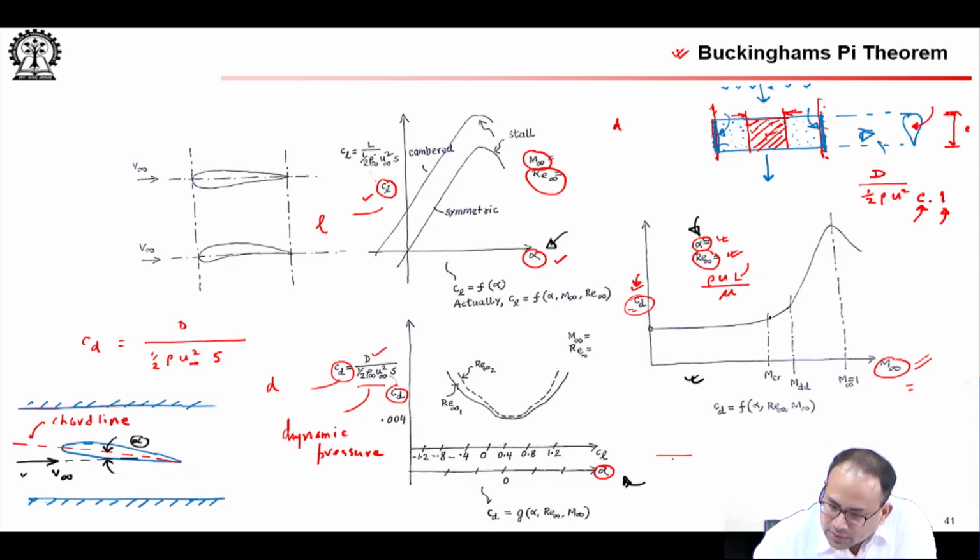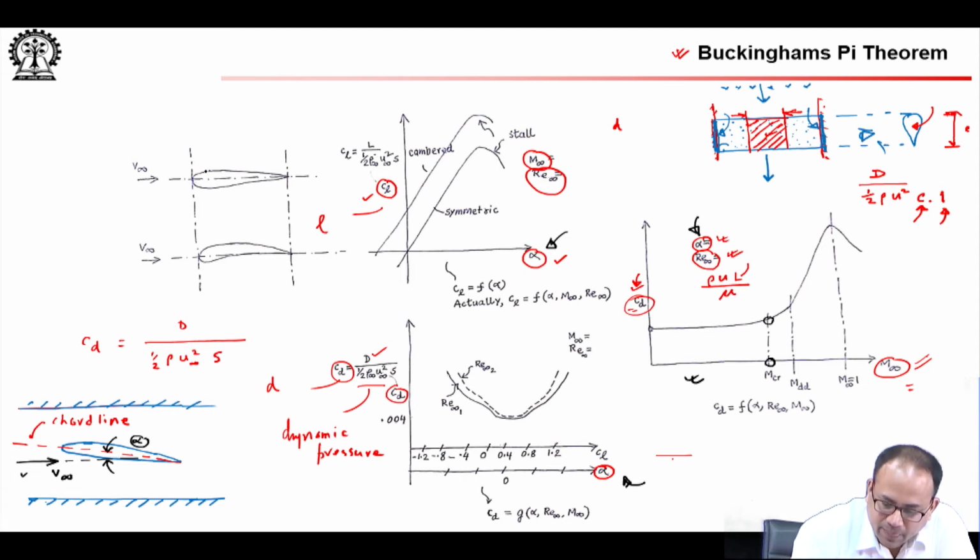Remember this is the Mach critical, the free stream Mach number at which a point on the airfoil reaches sonic condition for the first time. Experimental data has shown that, suppose you have maximum thickness here, for some airfoils the position of maximum velocity is located at say 11%.